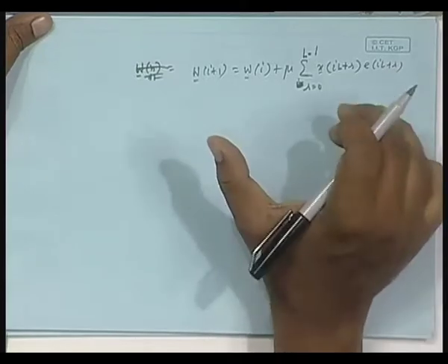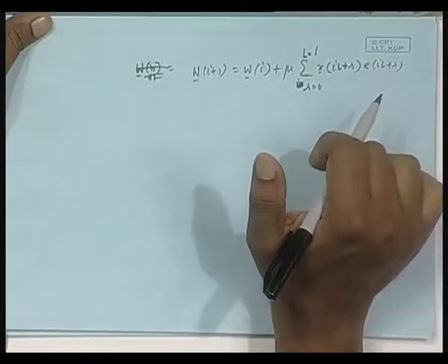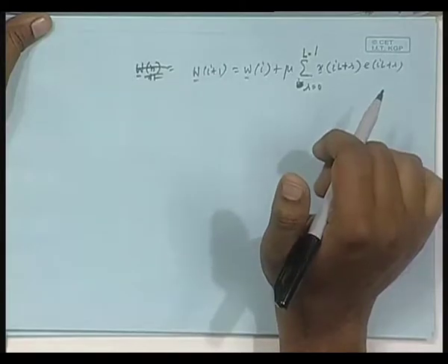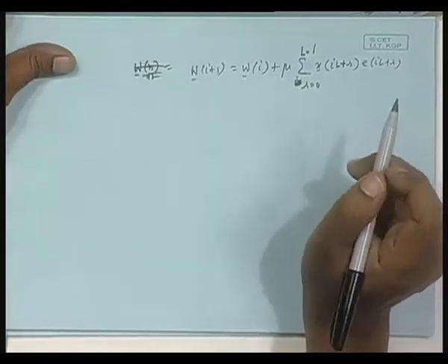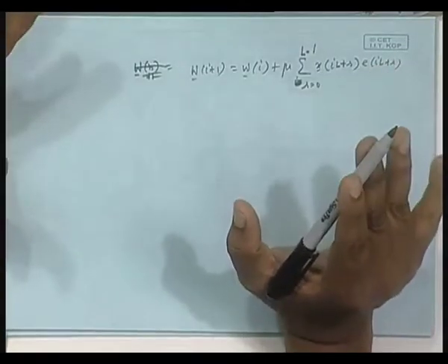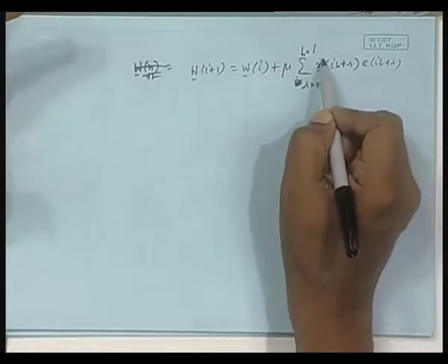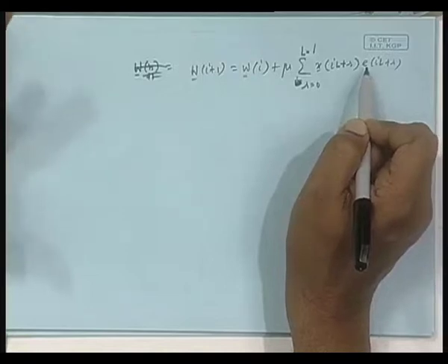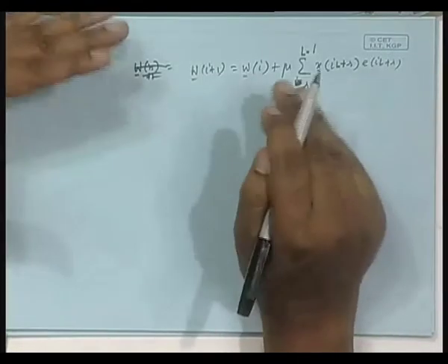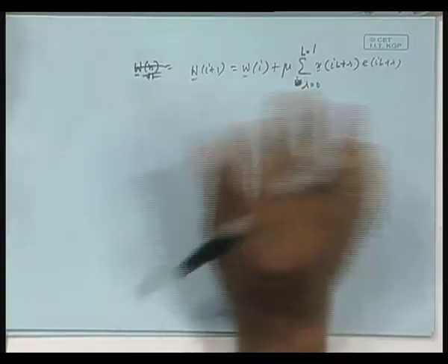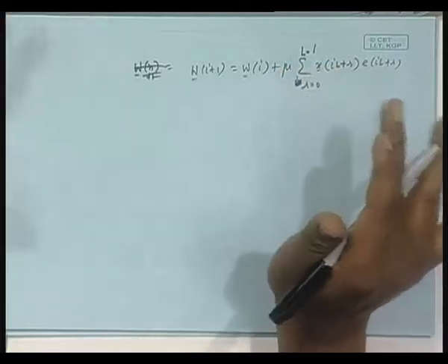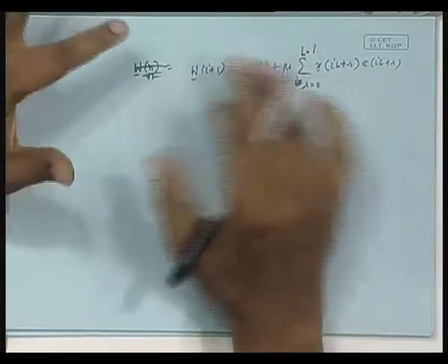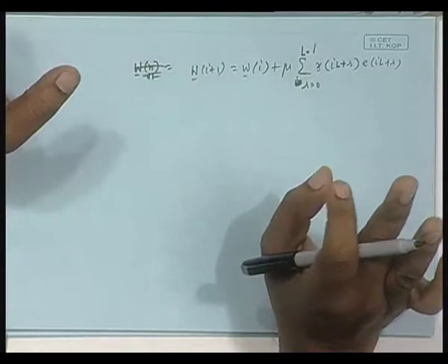By the way, if it were a complex LMS algorithm, the whole derivation would be the same, but there will be a star here, isn't it? X star, or star on x or star on e. We will be considering that extension, because when I do this FFT business, I will take care of that also when it is complex. For the time being, we are assuming real.